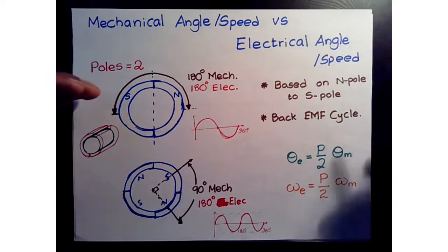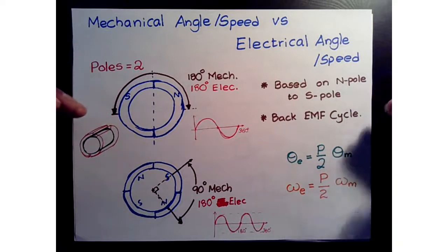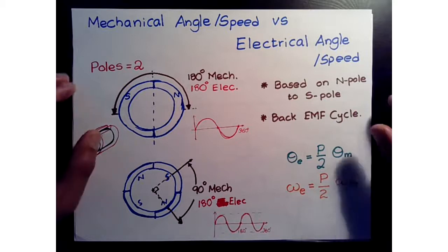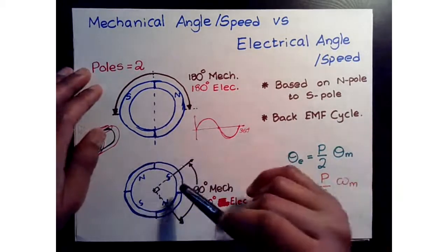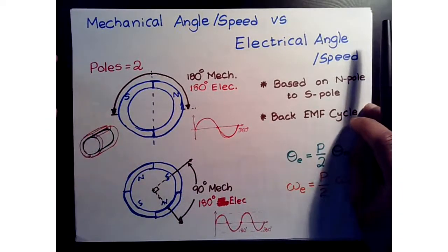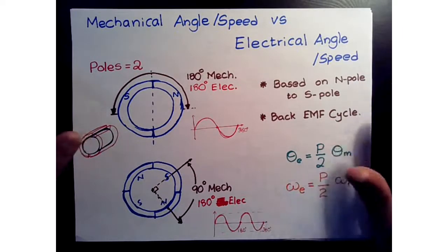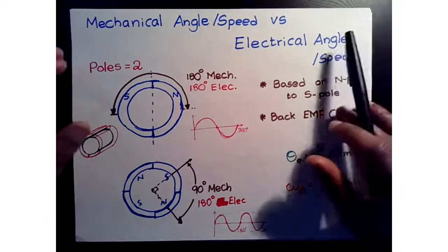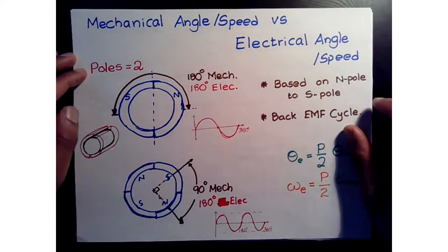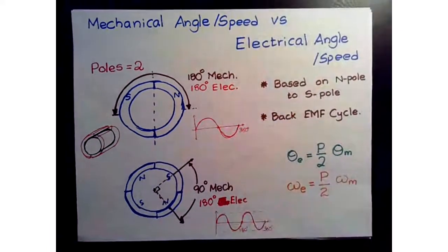Now, you're going to see motors of different pole count depending on the application. The machines are designed to have certain properties, and as a part of the design process you're going to see a certain number of poles. With the number of poles you are going to see a certain number of slots. So typically they will say this many slots versus this many poles: 12-4, 12-10, 12-8, and so on. You're going to see different numbers of poles, and I'm trying to highlight here the importance of those two types of poles.